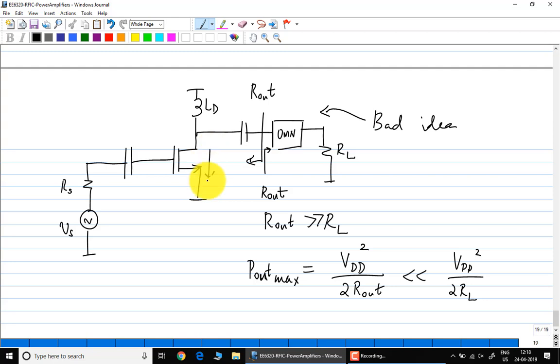The PA is normally going to take several tens of milliamps, to make sure that you don't burn up the wires that make up the inductor. The inductor is basically going to be a spiral, created using a metal layer. You folks have seen this. You're going to put out 40 milliwatts with a 1.2 volt power supply.